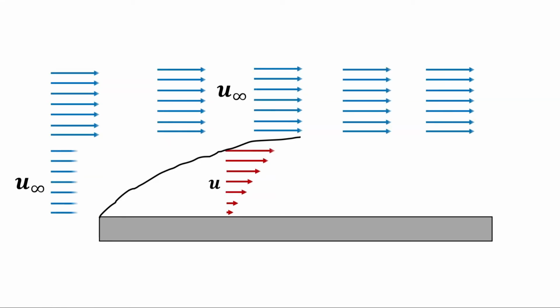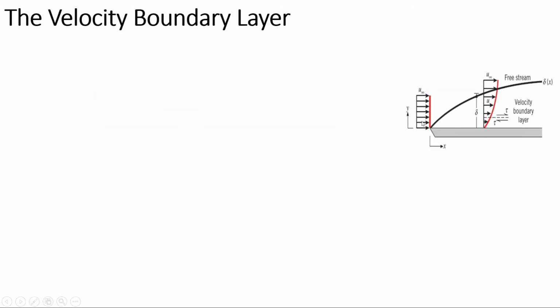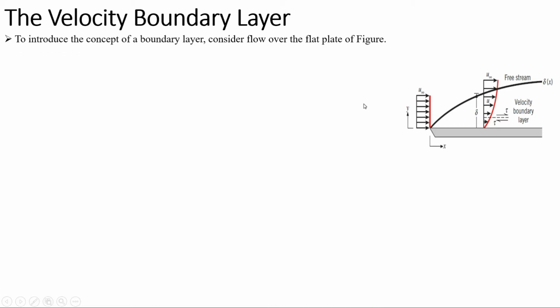You have learned velocity boundary layer, you just focus on the velocity. So this is basically the diagram. This is the free stream velocity approaching towards the flat plate. This direction is taken as x, and this vertical direction is taken as y, and a layer is formed, which is known as velocity boundary layer, in which the viscous effects are significant. Within the boundary layer viscous effects are significant, and outside the boundary layer viscous effects are negligible.